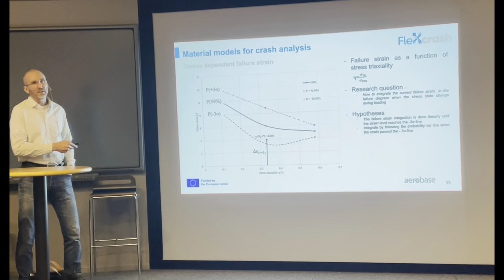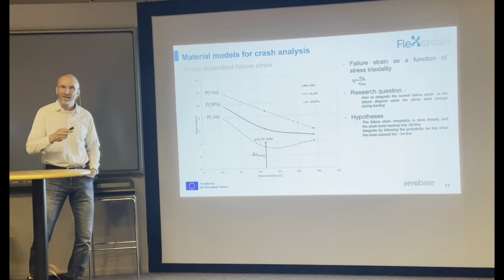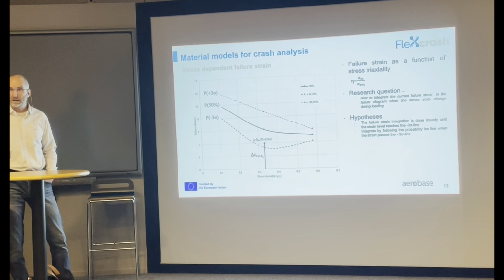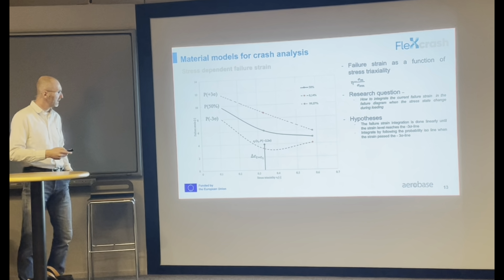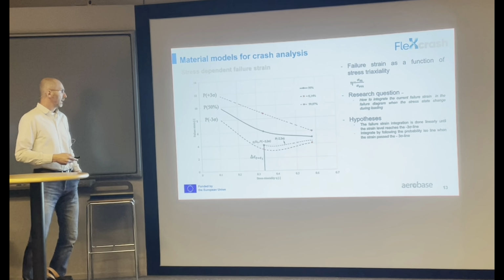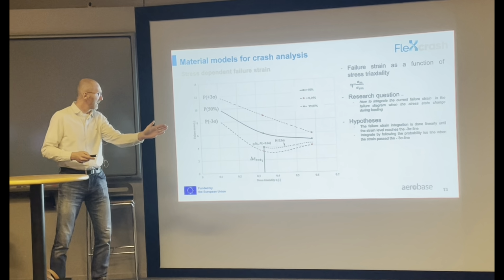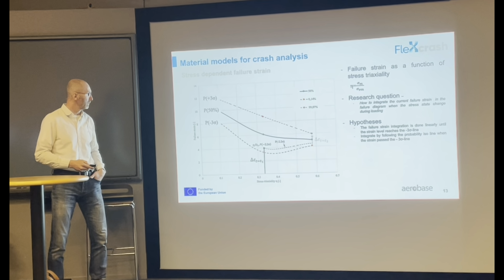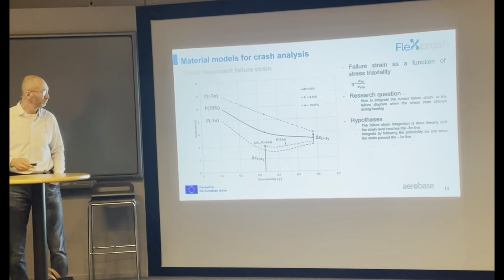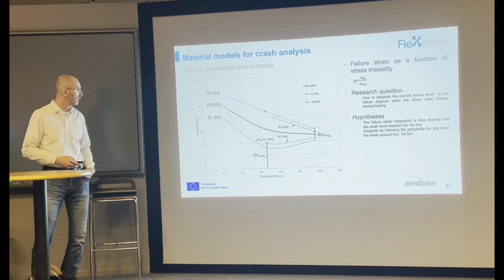The other condition is that when we deform more in the first step, so we pass this -3 sigma line, then we are in the world of probability. So we need to take care of that in another way. So what we do then is that we follow the isoline. When we then change the stress triaxiality, we start with the same probability in the next step before we take that additional strain step. So that's the hypothesis, and that's something we need to prove in this project.